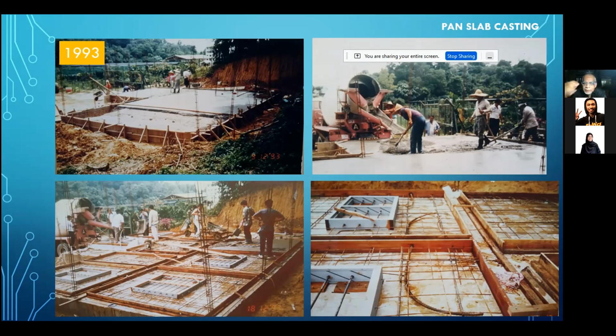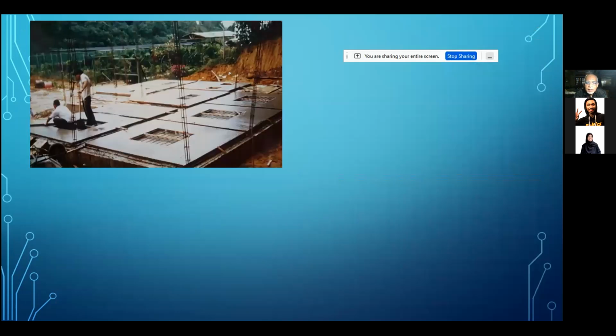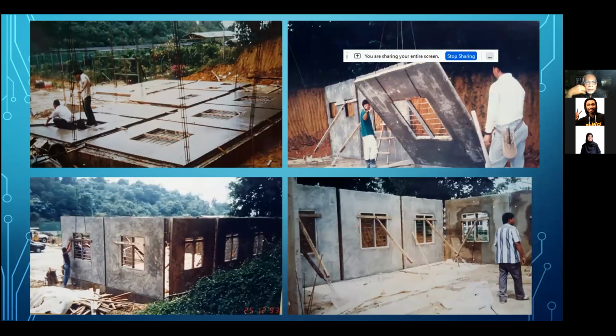And then I put the last slide here below, this lifting bar, the big lifting bar there, so that when I lift, it doesn't break at the corner. So that big bar is for the purpose of lifting. And that is how smooth the wall is when you cast on the ground on a flat area, compared to when you do plastering on a vertical surface.